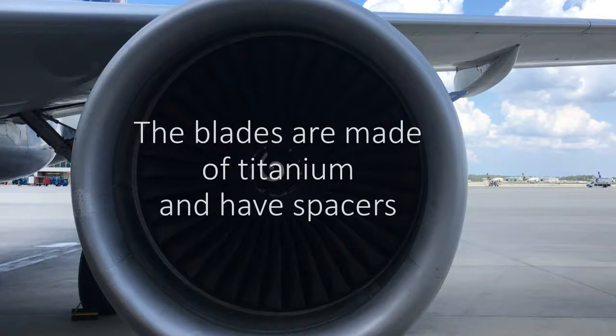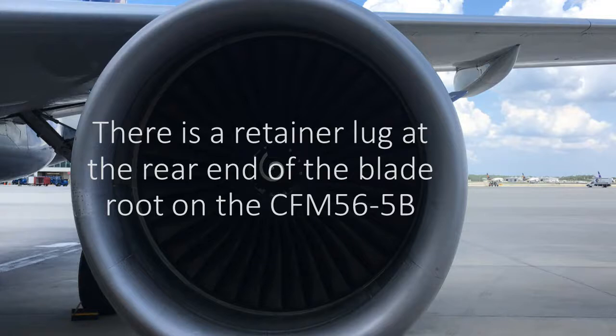Okay. Now, the way the blades are, like I mentioned before, they can come in pairs, and be aware of how that has to be installed because of that. There are spacers that are actually underneath each blade, and those need to be there because they limit the movement of those blades to a certain degree. The little difference you might find with the Dash 5B is a retainer lug at the rear end of the blade root.